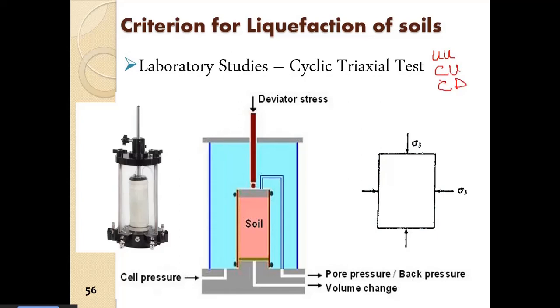And we observed that especially the consolidated undrained shearing is particularly applied for studies of soil liquefaction. This particular test is mostly applied. How the pore pressure develops and how it leads to reduction in effective stress, this particular type of triaxial test is most efficient in simulating the various conditions. So we started with the triaxial test.